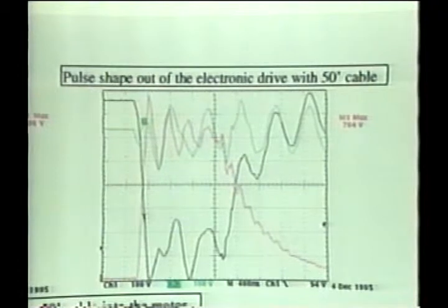Again, only look at the pink curve, and you can see the fast oscillation typical of what results from PWM operation when there's an impedance mismatch. Now, the measurement point for this particular curve is the same as the previous one. If we now move the measurement point to between the specimen and the cable, you will again get the oscillation.